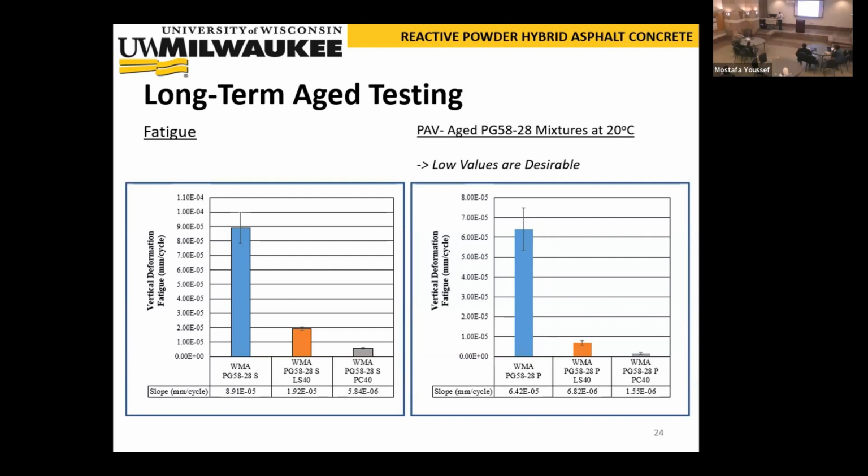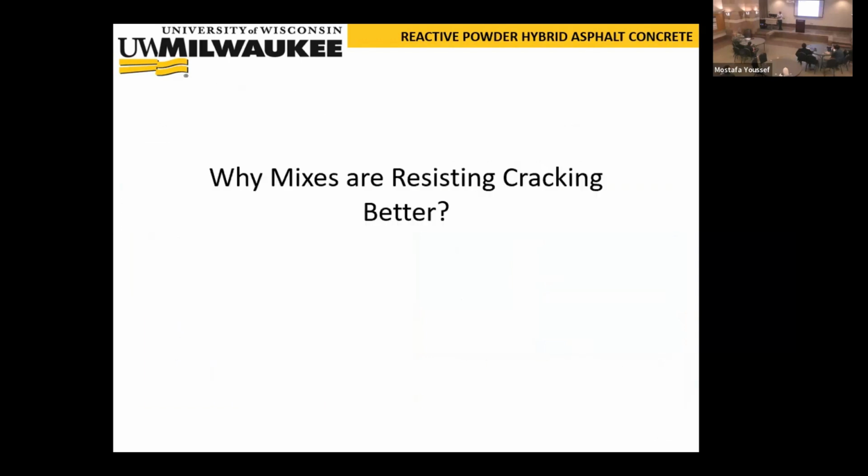and thinking this is the determinant parameter. But once you get to the mixture, the dynamics of the failure and the stress distribution are very different. Even the dynamics of the applied tests are not exactly the same. They are very different from the binder testing, which is more rheology based and less damage based.